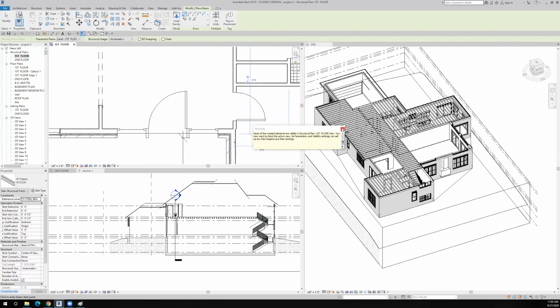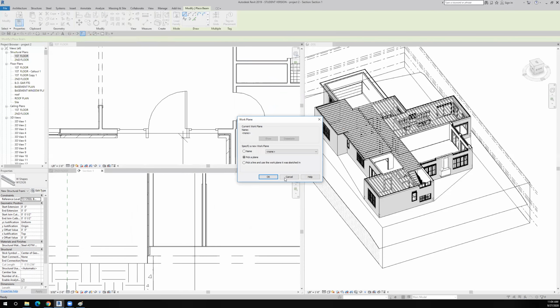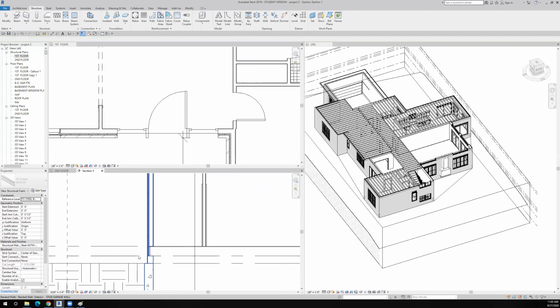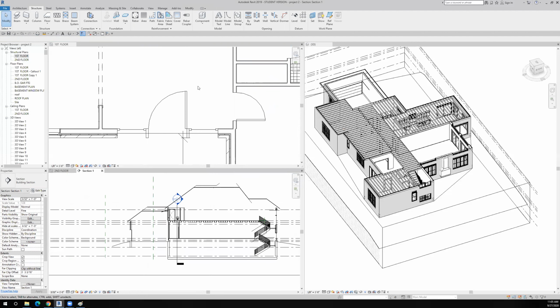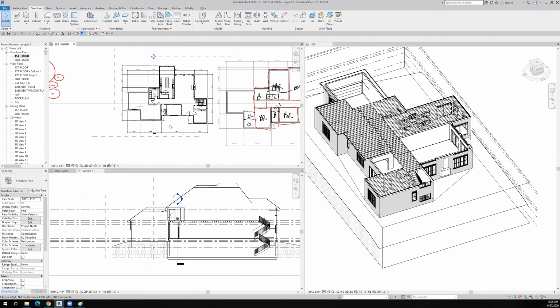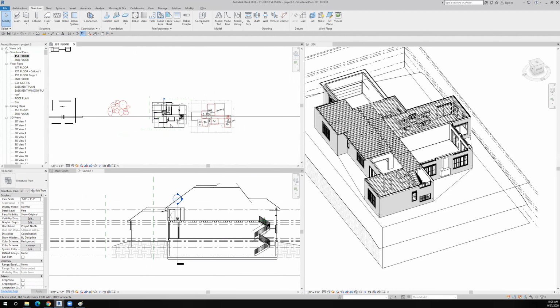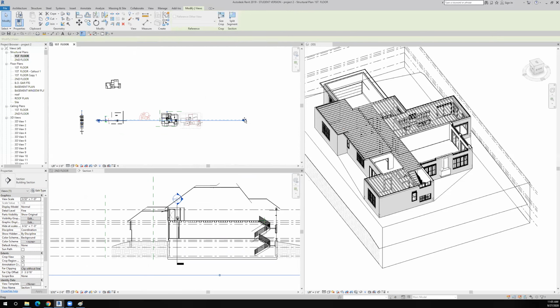So the steel beam rests on the basement wall, and what they do is they actually put what's called a beam pocket in the top of the basement wall to allow us to actually put our steel beam in there. So let's zoom out. I'm looking to see a section through my house that shows me, well, look at what I did here. I made this huge section all the way across here.